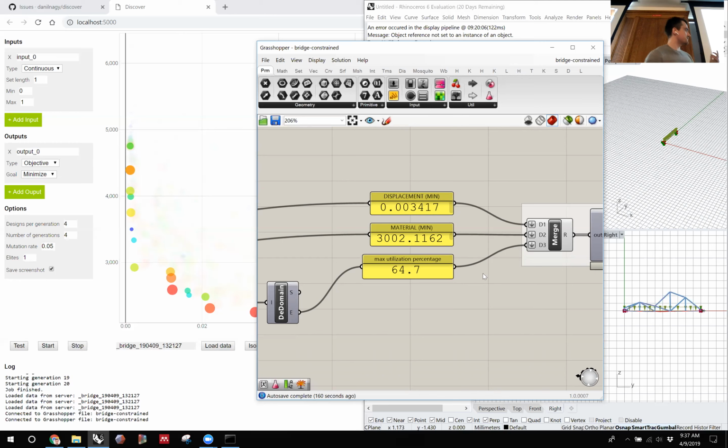Right? So if we want to optimize for a safety factor of 2, we would limit that maximum utilization to 50%. Right? So say that a successful design is any design where none of the members are more than 50% loaded. Does that make sense? And your safety factor typically depends on your context, like how predictable or unpredictable the simulation is versus real life. So I think with engineering applications, a 2.0 safety factor is typical, but with buildings, it's a much higher multiple safety factor. So there's a lot of aspects of the building structure that are really hard to predict in real life.